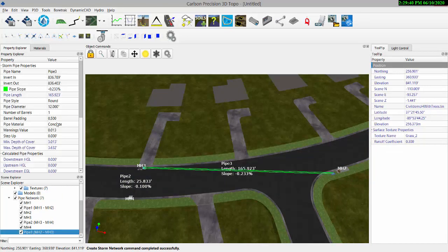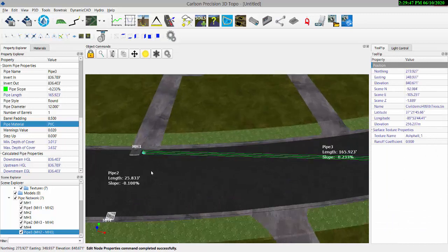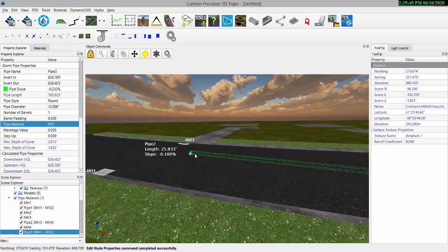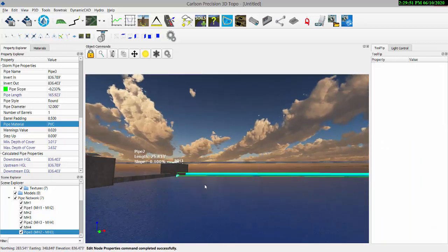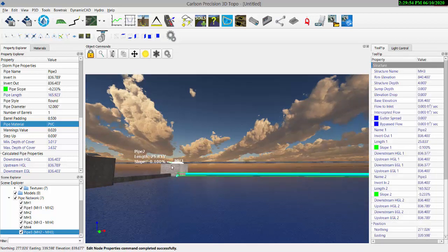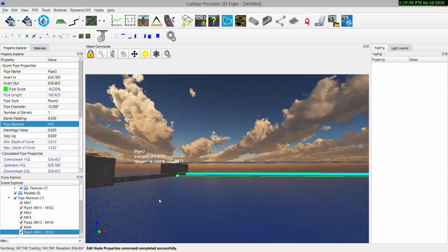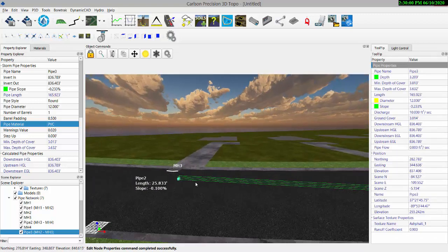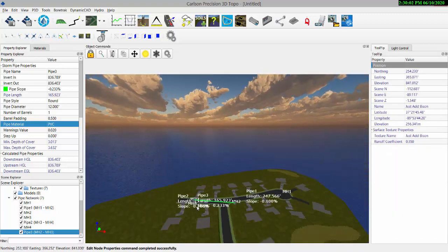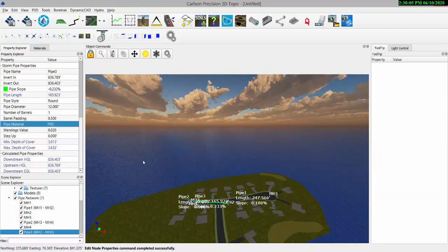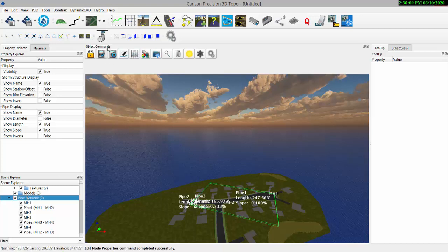And you can come here and even change it to PVC, a different material. Now you can come in and look at it perhaps underneath and see we've got a blue PVC pipe entering this inlet with a standard default concrete pipe. The next thing you might do, of course, is finish out to the head wall, and then by selecting pipe network, follow up with a hydraulic analysis.